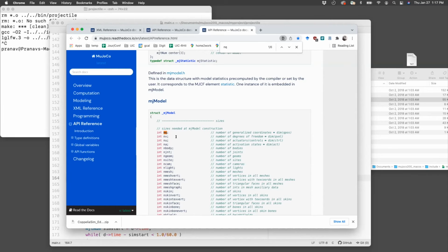What is NQ? In this case, I know it's a free floating object. That's all that is in the scene. So NQ for this has to be the 3 translations and 3 rotations. And it turns out that MuJoCo doesn't like to use angles for the rotations, they actually use quaternions. There are 4 for quaternions, and so NQ should be 7.